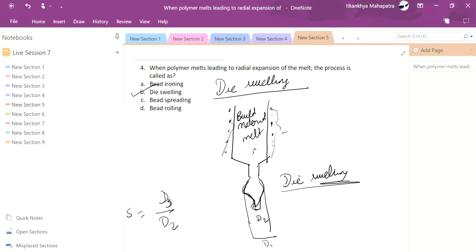The nozzle will be clogged because there won't be enough space to print. So that is why we always give some amount of buffer according to requirement. And we also always check the print velocity. Suppose the print velocity is very large, the bead will become unstable and discontinuous.